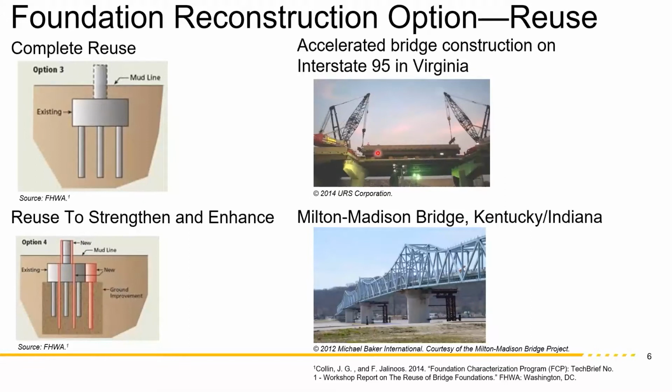And then on successive weekends, they brought in prefabricated bridge elements and they demolished and placed them in section by section. So they only maybe closed the traffic 3-4 hours. That's I-95, and they did it just on the weekends, and it involved 11 bridges, and the total saving was $60 million from reusing foundations.